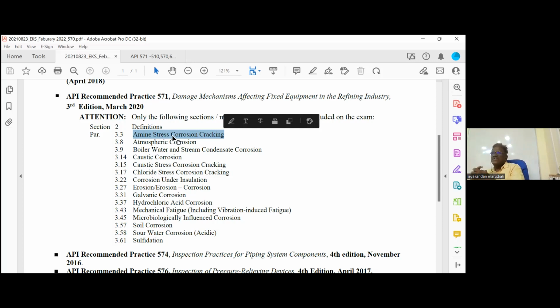Those are easily detected. Ultrasonic, again, is the opposite. Ultrasonic is best for planar defects. UT can miss a volumetric defect. Okay, you know these four.